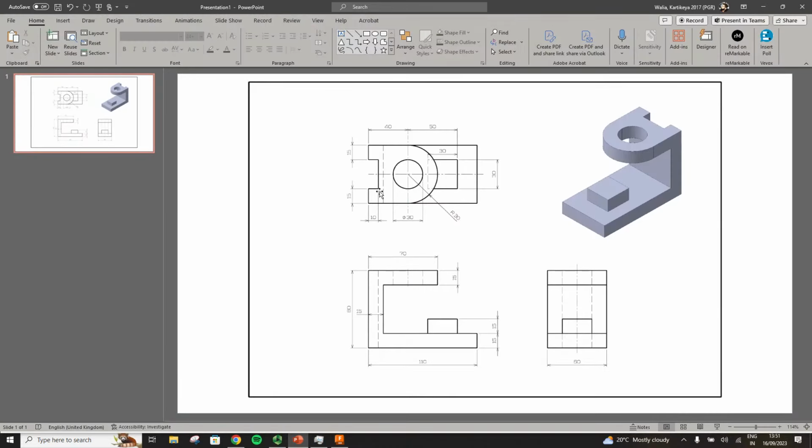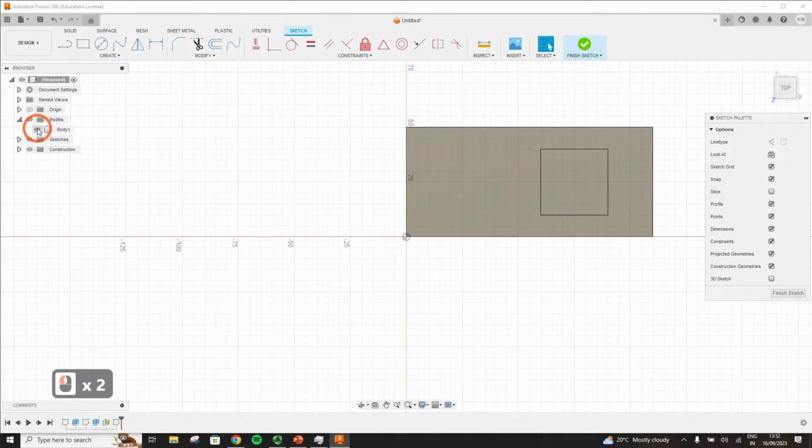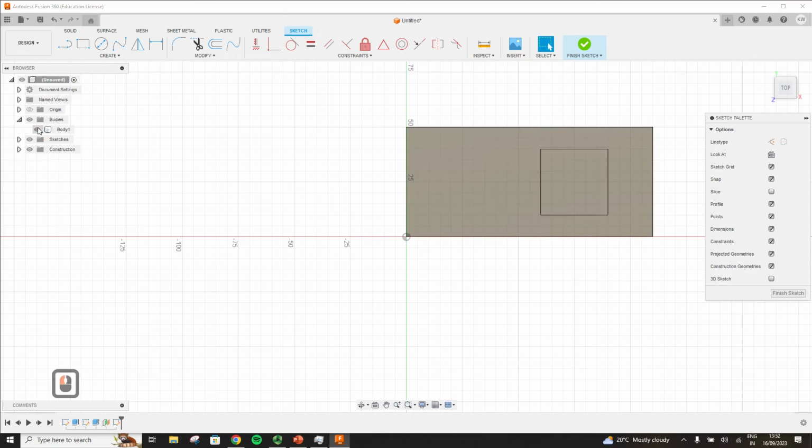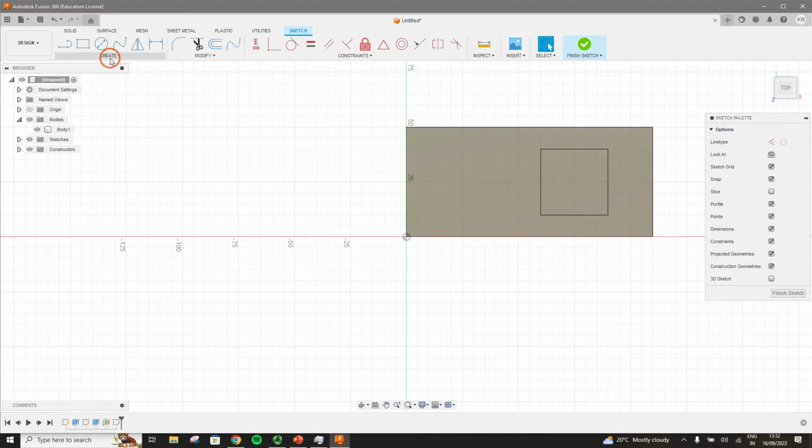So we are aiming to make this shape. We have a circle at a 40 mm distance from this point. So we have this circle of 30 dia. Actually going to see that. So one thing that might help, because we've already hidden the bottom plane, and from here we can see another command as well, which is project. We can get some of the edges from the previous 3D model into our current sketch. And that is done using project.